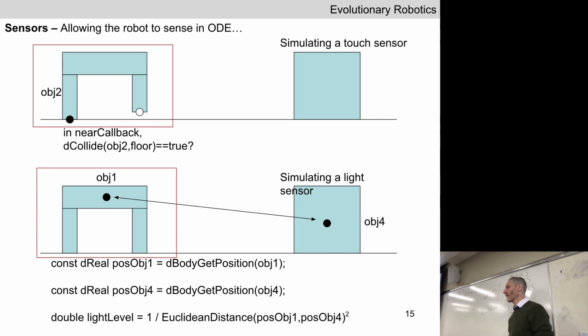What about line of sight or occlusion? What about line of sight or occlusion, right? There's nothing in here that simulates that. So if this robot moving around ever comes, if an object ever comes between the robot and its light source, that evolved behavior is not going to transfer from simulation to reality. So let's go back in and elaborate the code that we use to simulate the amount of light falling on a light source at every time step.